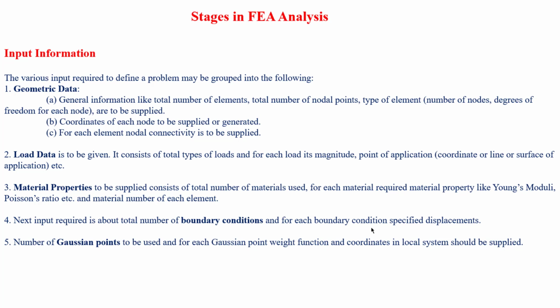So like this, the material properties also we need for input information. Next thing, whatever things you want to specify, after that we need to define the boundary conditions, right? Where it is fixed, whether it is something related to crash analysis or impact analysis or the drop test, the fatigue or whatever it is.